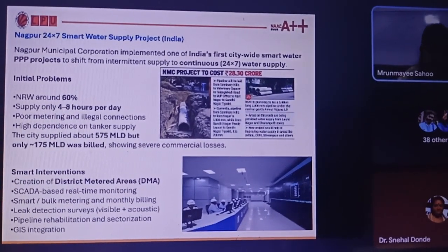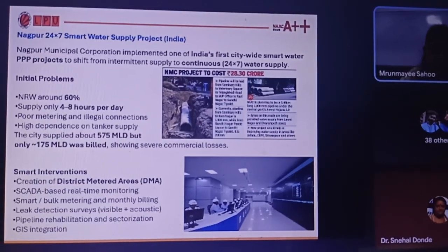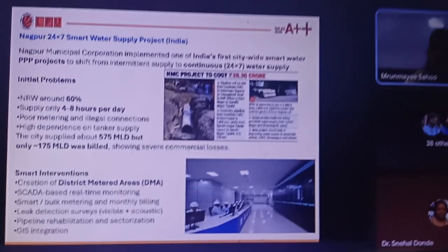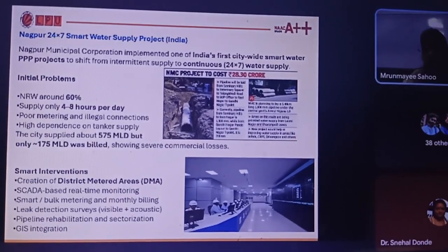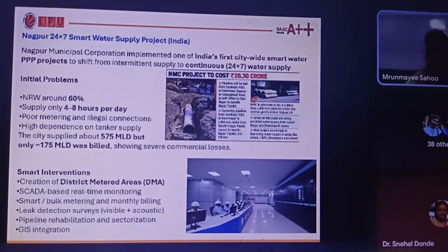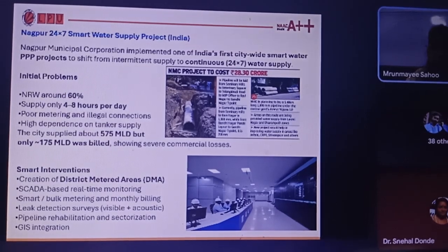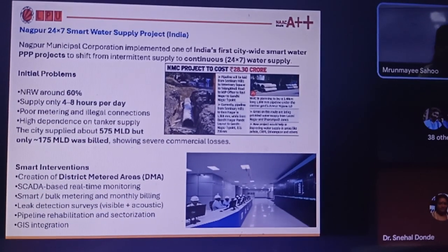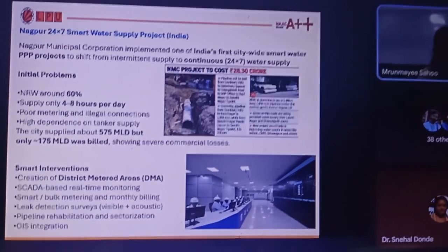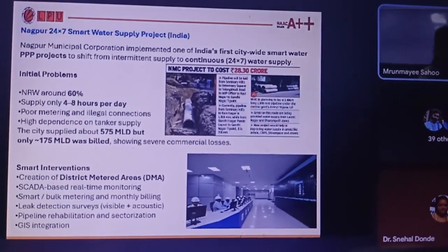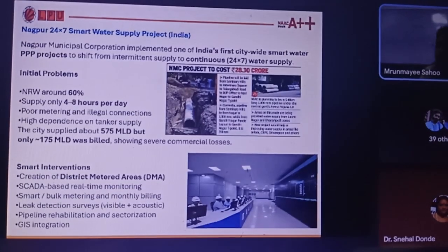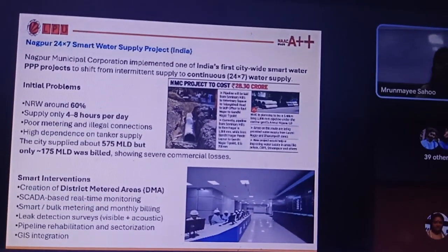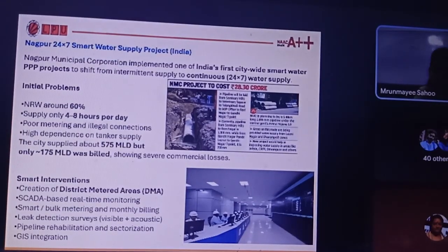Similarly, right now Nagpur is seriously taking up pipeline rehabilitation, renovation, checking of the sensors and flow meters, and maintaining the pressures. Like I've said, we have a pressure sustaining valve. So if you complain, like, in my house pressure is very low, we will check. We are supplying water to you, but in your house the water pressure is lower, and our sensors are working, everything is working, no sedimentation. How is it possible? In those cases we will put a pressure sustaining valve in your area.